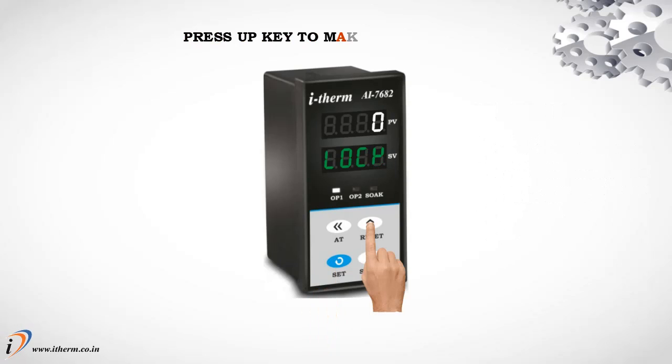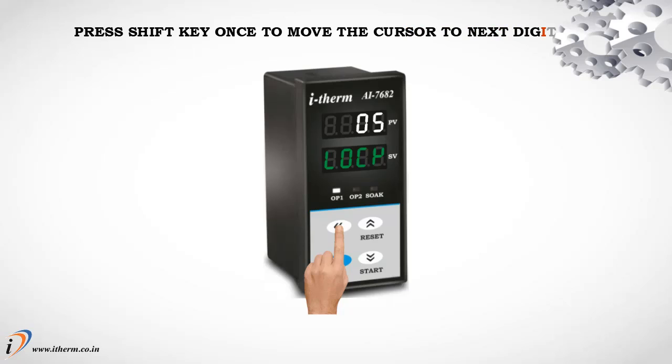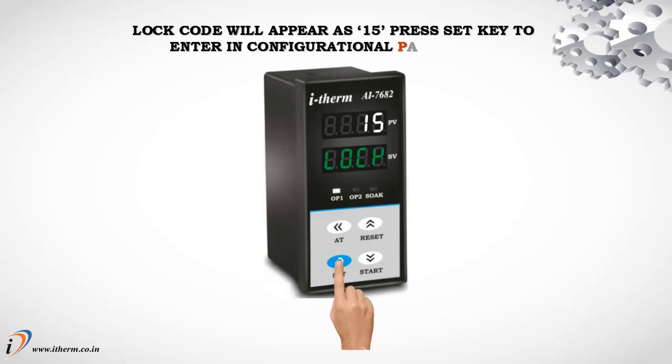Press the Up key to make the unit digit 5. Press the Shift key once to move the cursor to the next digit. Press the Up key to make the unit digit 1. The lock code will appear as 15. Press the Set key to enter the configuration parameters.